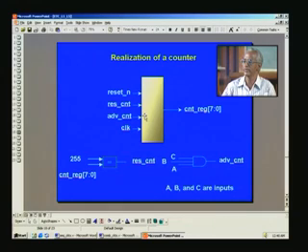And if you want to reset when the counter reaches, say, 255, in this case it may sound redundant because the next value will automatically be 0, it will wrap around being 8 bits. But any other number you want, you can also use. That is why it has been put in a general fashion like this, right. And there must be a clock and a reset also, because all flip flops normally need a reset, a power on reset as such.